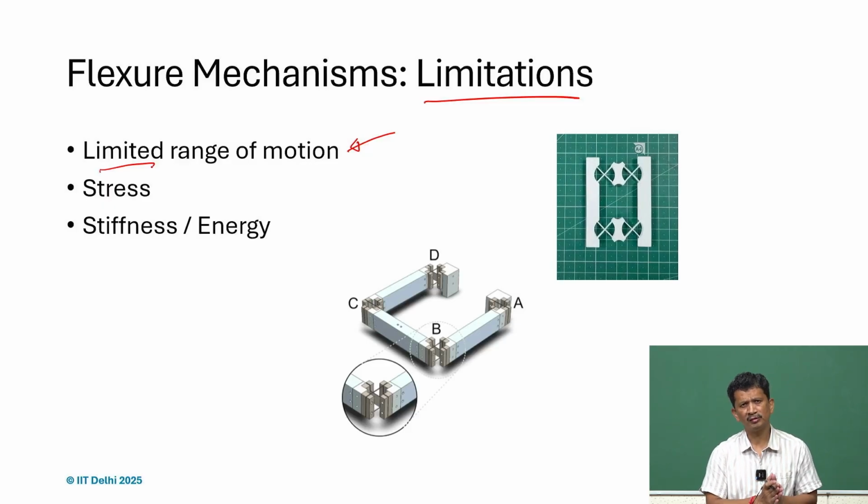What is also important to understand is that we can always build these mechanisms on top of regular mechanisms or mechanisms with coarse movement. Any conventional design, like a ball screw or the linear guides that we have, although in today's time we can call them precision, when we are talking about 1 micron kind of precision, they may not be precise enough.